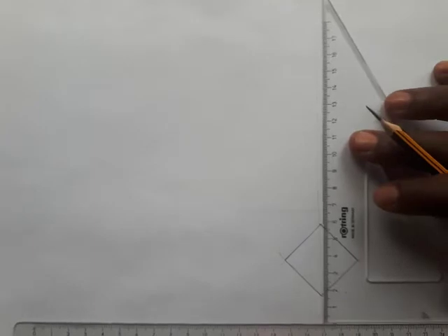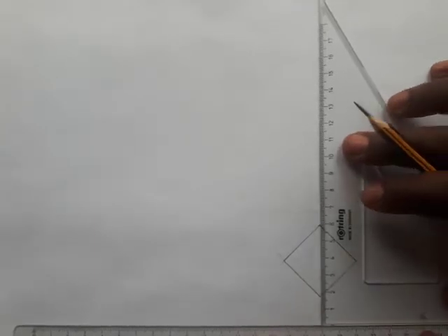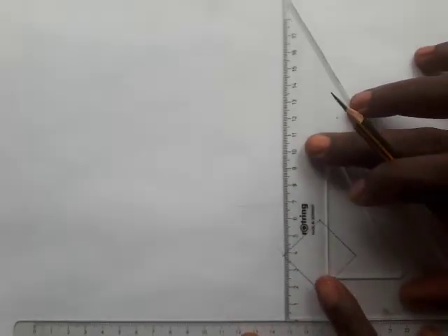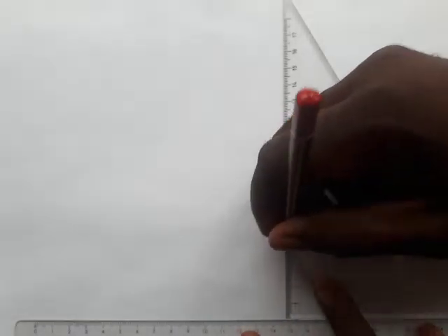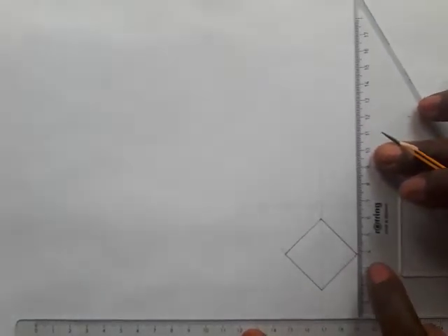All right, now align your set square in this form with this center line. Make sure you align with this center line, you support with your ruler, slide to this point here and draw a thin line up, slide to this point here and draw another thin line up. So that's it. Now let's check our dimensions again.